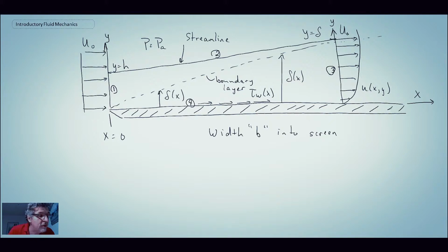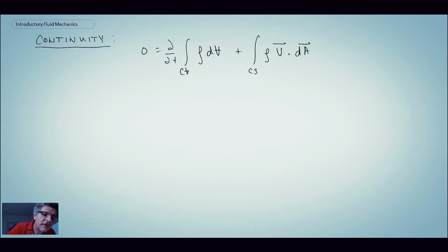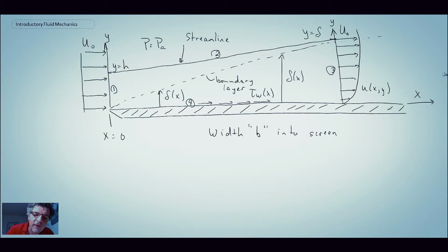So what we're going to do, we're going to begin by looking at the continuity equation, and then we'll move into momentum. So we'll take a look beginning with continuity. So it was a steady flow field that von Karman was studying, and consequently that term disappears. And then for the mass flux, returning back to our schematic, there would be mass flux coming in here, and then mass flux exiting at 3. And given that he put the streamline being on the upper surface and the wall on the lower, there was no mass flux on either of those surfaces.